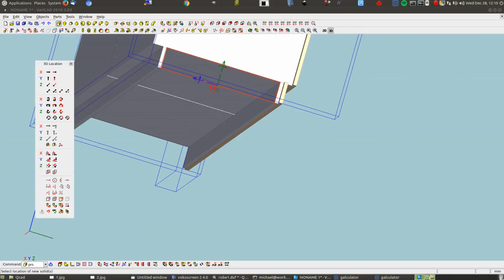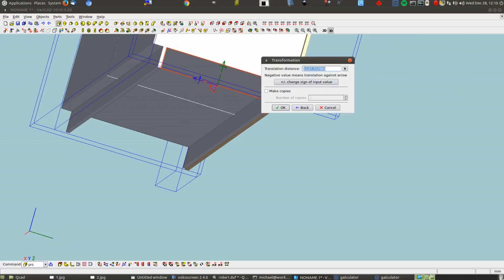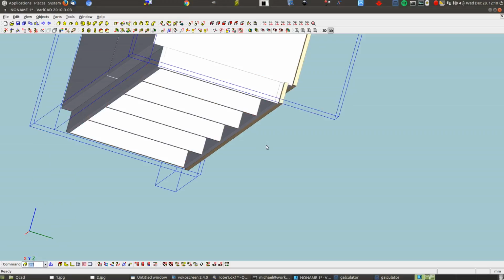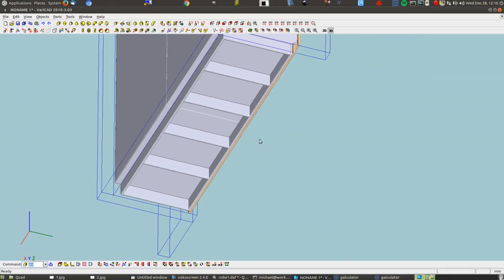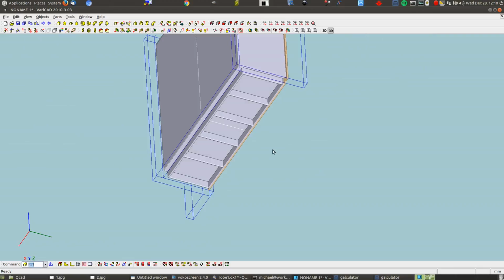What I'm going to do is copy. I want 5 copies. Now we could again type in 2220 less 16. Put brackets around that. Divided by 5. Okay, and make 5 copies. If you struggle with the mathematics, I'll show you the other method. As you can see, bang, we got that there. They're all there. I'll zoom out. So that was that. I'll go undo that.